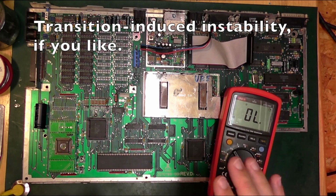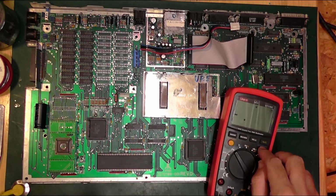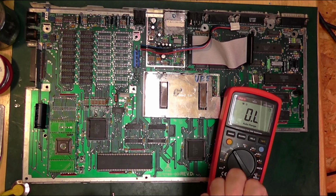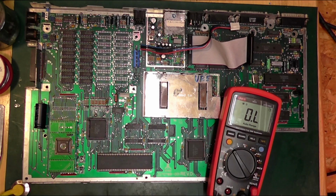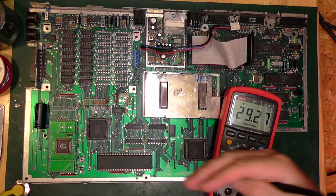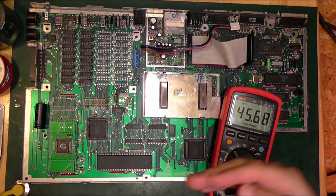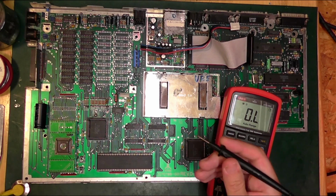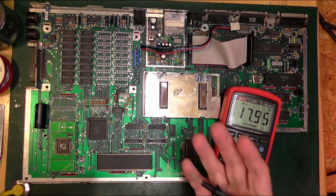So the way you work around this when you're designing the boards, and this is not anything to do with retro hardware, this is still in common practice today, is you apply pull-up resistors. So all of those data and address lines will at some point have a resistor between them and normally you pull up, so them and the 5 volt line, which will bias them high.